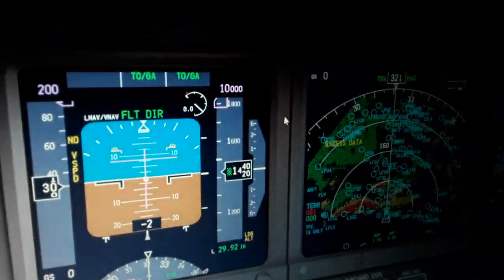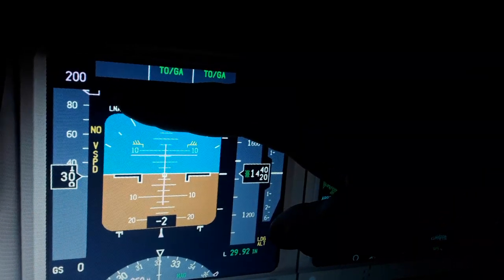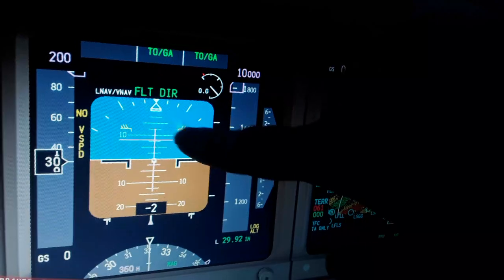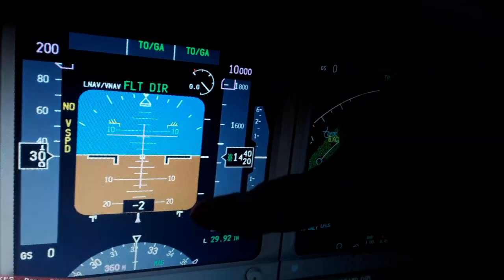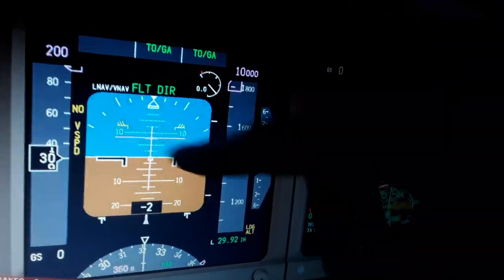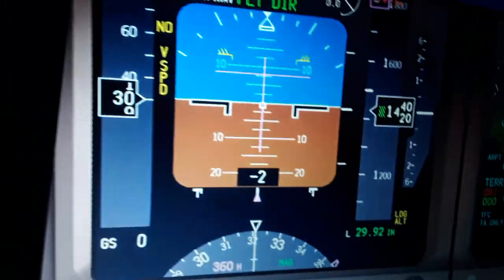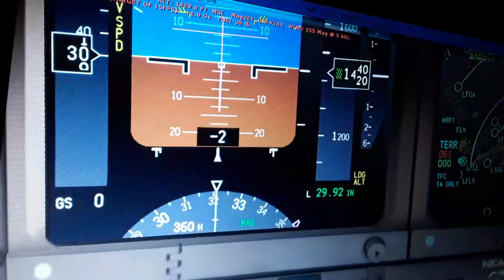You can see the airspeed selected from the autopilot and flight director system, the ground speed, the crossbars from the flight director or the autopilot with the flight guidance of the aircraft, the radio altitude, the LSZH localizer for an LSZH localizer landing. So you can see these limits here represent the takeoff speed limits.